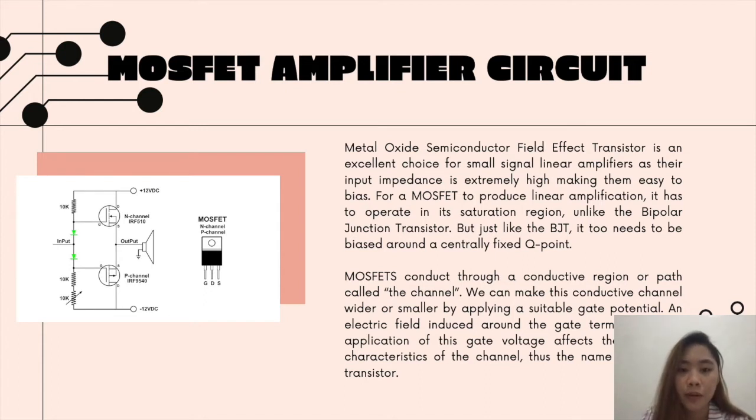Furthermore, MOSFETs conduct through a conductive region or path called the channel. We can make this conductive channel wider or smaller by applying a suitable gate potential and electric field induced around the gate terminal.